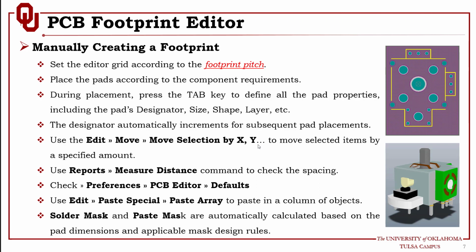Altium Designer also provides a paste special feature under the Edit menu, where you can paste a set of holes into the footprint based on a specified distance or number of occurrences in X and Y, like creating an array of holes. This will simplify things, especially when you create a connector, for instance. It's very handy for that kind of footprint, and we will take a look at that as well.